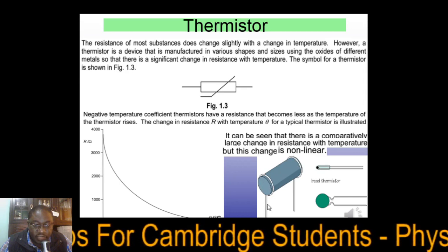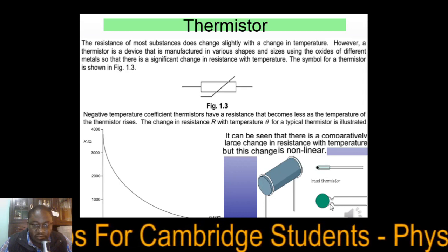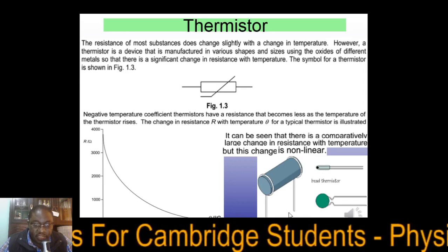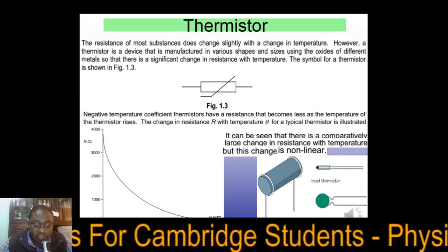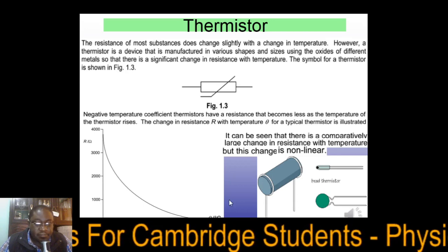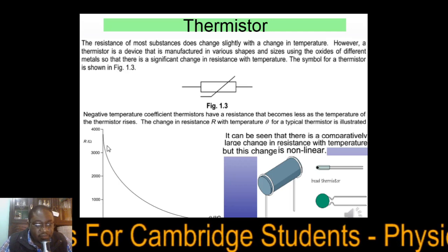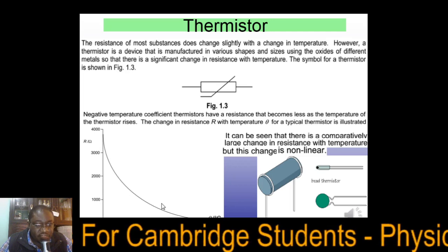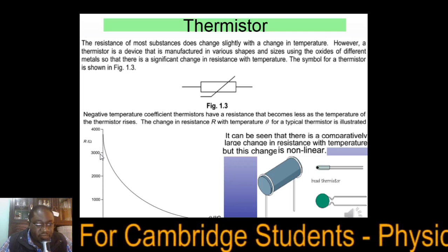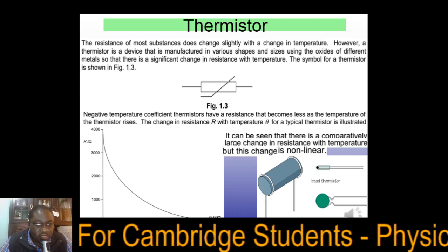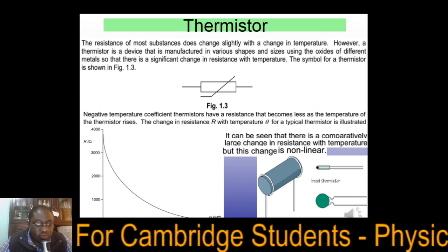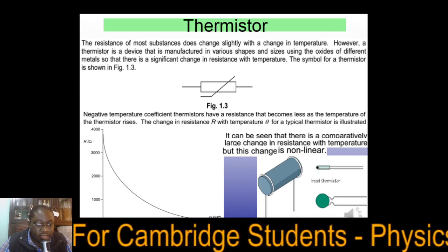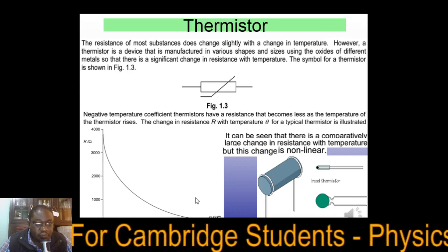And you have the thermistor shown in real life. That's what it looks like. That's a rod thermistor. And then we've got a disc thermistor. And then we've got a bead thermistor. So you just connect them in the circuit by using these contacts. Again, the resistance against temperature graph is that of negative temperature coefficient. In other words, when the resistance is high, the temperature will be very low. So at low temperature, resistance is very high. At high temperature, resistance is very low.